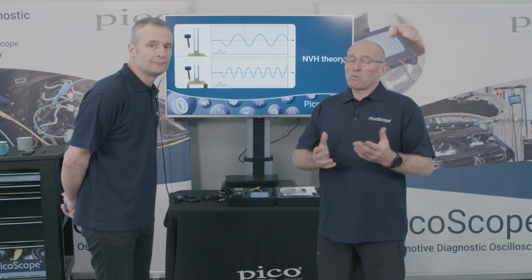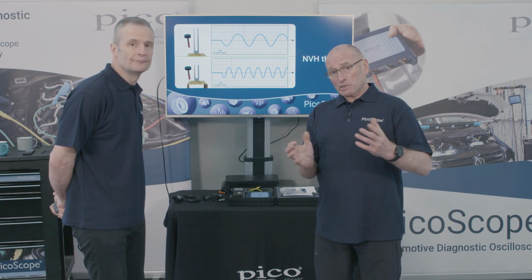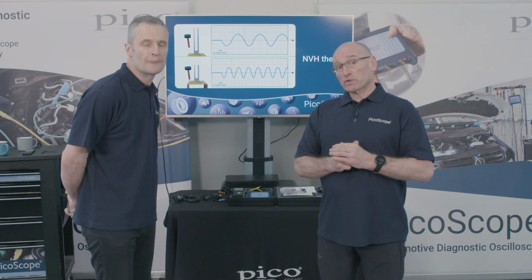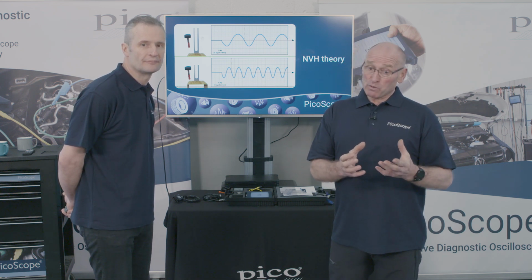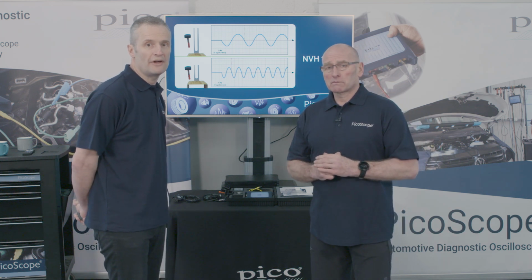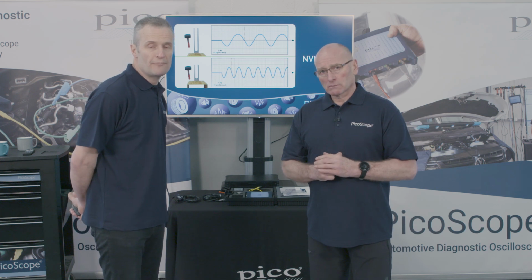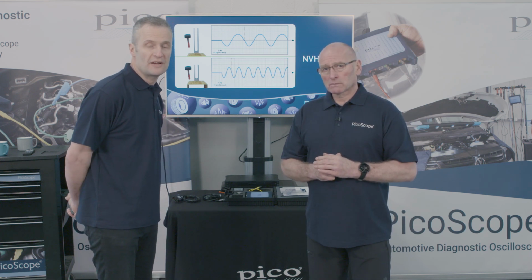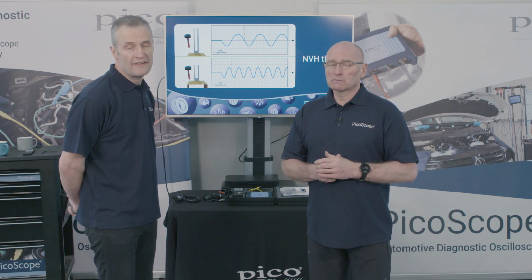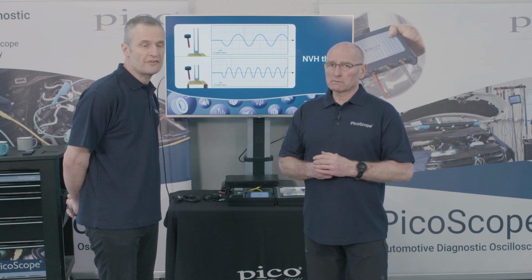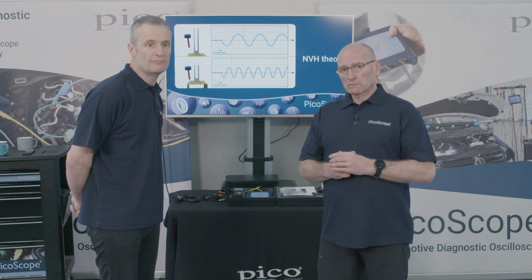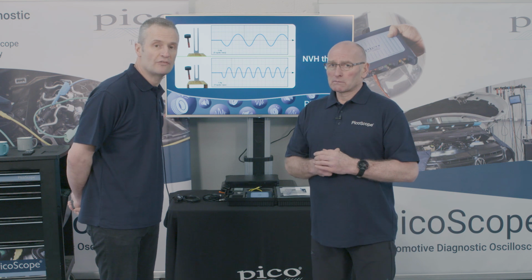So what we've done here in effect is we've taken a vehicle, we've put some sports suspension on it, we've lowered the suspension, and we've done exactly what that animation has just shown us. We've changed the natural frequencies at which that vehicle now will demonstrate vibration. Yeah. The rigidity, if you like, has changed. So with the tuning fork example, the way in which that vibrates, it will now be a higher frequency. It's a stiffer, more rigid fork. Relay that to the chassis. The benefits of a stiff chassis is great driving feel, great feedback, but the downside of that is more passage of vibration or transfer of vibration into the cabin.